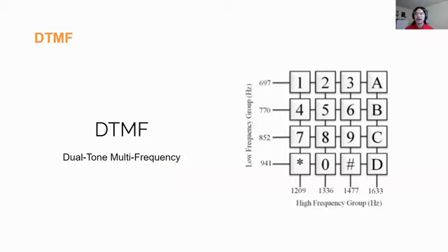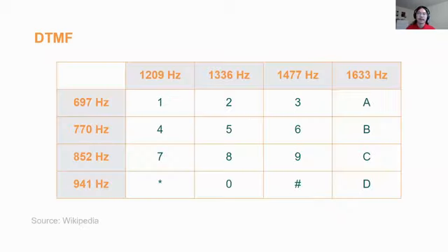What's special about this keypad compared to the one you see on the phone is that you have A, B, C, D, the extra 4 keys, which make up the entire set of DTMF, while the phone only has the 12 keys, because A, B, C, D are basically reserved for net control and other use. But anyway, on most HTs nowadays, even including the UV5R, you actually have these keys. So that's great. And just in case you're interested, these are the precise frequencies and the symbol table that you can look up on Wikipedia.